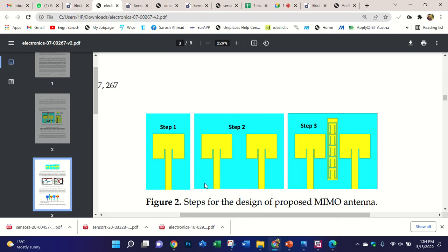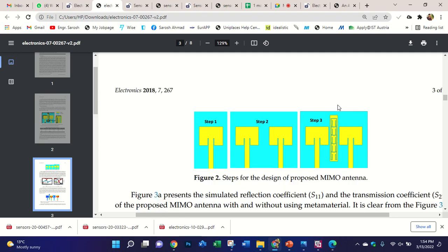In metamaterial and AMC we also use the same size as the antenna or maybe larger. But here in HIS maybe they use a small number of unit cells just to get some difference in results. Maybe they introduced this technique to improve the mutual coupling of the MIMO antenna.